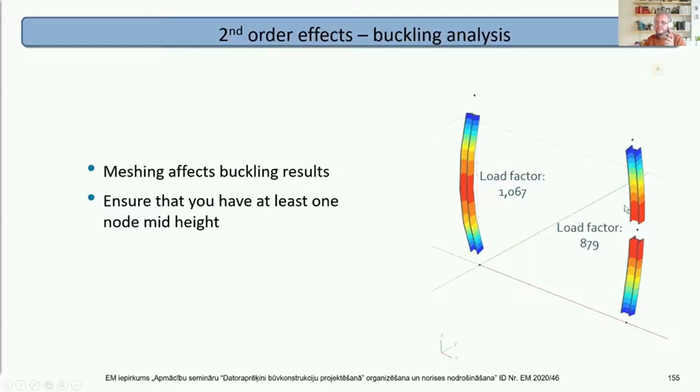Now, the reason for this drop is because the way that buckling analysis works, it's looking at the translation or rotation of the degrees of freedom, which are the nodes. And in the first option, there's a node at the end, and it's looking at the rotation on a node, which then gives us zero axial stiffness.